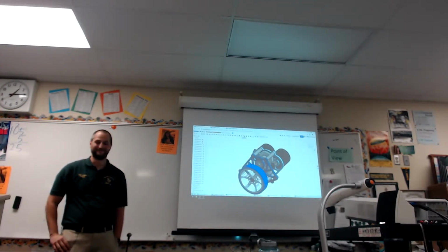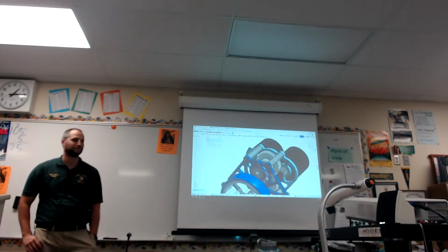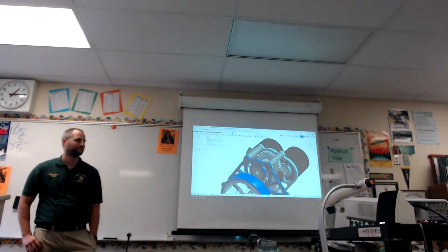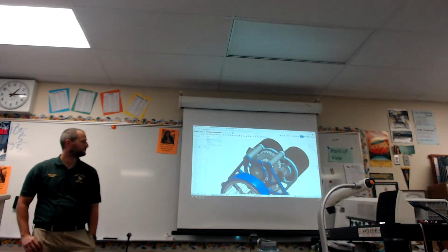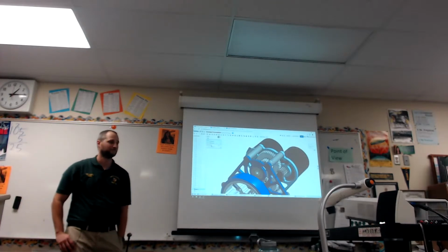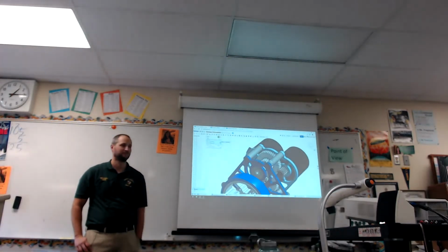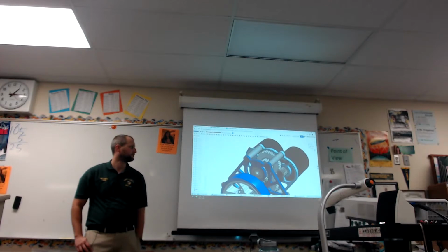There actually is. There is this gear relation constraint in the assemblies, and you just have to select which mates you did. So if you used a Revolute mate, I'm just going to go to one I already did. As you can see here, I had to click on the Revolute mate, which is the mate that makes the gears actually spin, and then you just put in the gear ratio. So it would be the first mate you clicked on over the number of teeth in the second gear that you click on. Then you type it in as an equation, and you can rotate the gears, and now they function like actual gears.